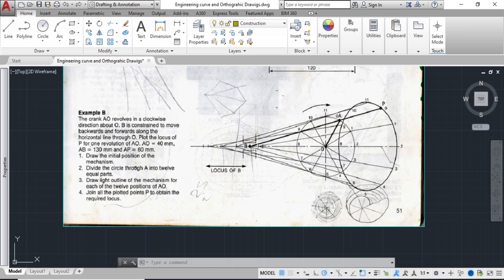However, we are doing AutoCAD drawing, and we know plain geometric drawings are difficult in AutoCAD because the program was not designed for plain geometry. It was designed to solve all those problems without having to solve them manually. The reason we had to do these drawings on paper was because we didn't have computers. Now that we have computers, the syllabus has not changed, so we still have to keep fooling ourselves, but let's continue until we don't have to anymore. So what you do is use center start end, put it at 2, open to 130, and scribe. Use the center start end arc.